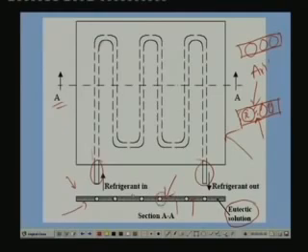In another method, this space is not filled with any solution, but it is evacuated. When you evacuate it, the outside pressure, which is atmospheric, presses these two outer plates onto the tubes. As a result, again good thermal contact is formed between the tubes and the plates. But more widely the eutectic solution is used, because the advantage of eutectic solution is that in addition to providing good thermal contact, it also provides what is known as hold up capacity.